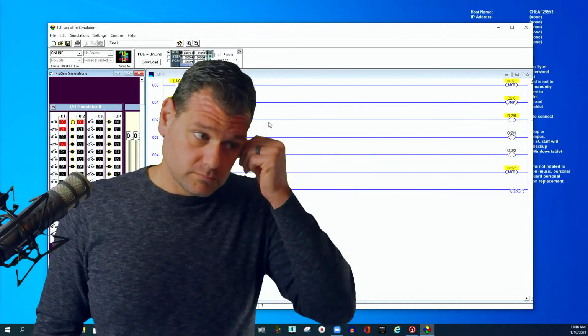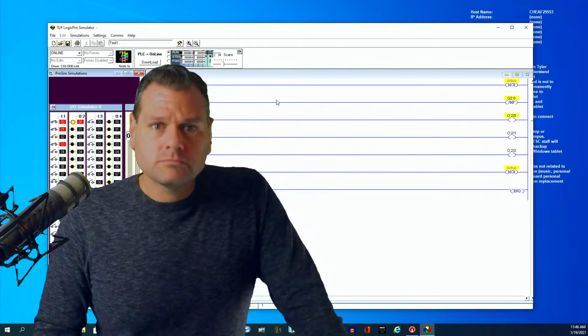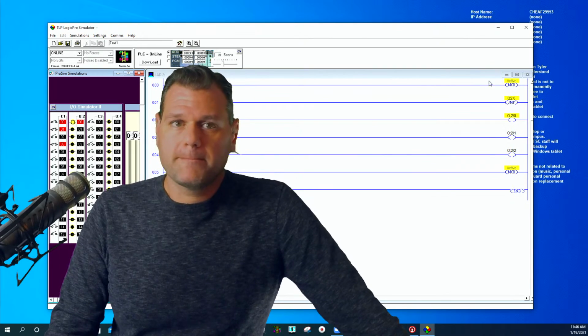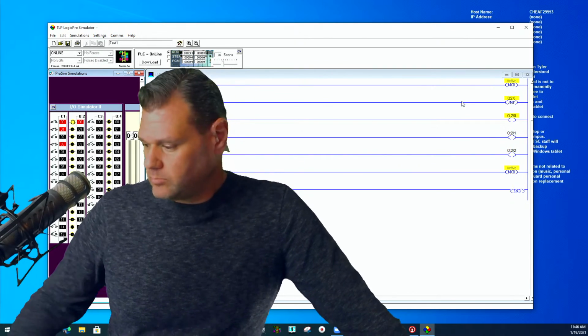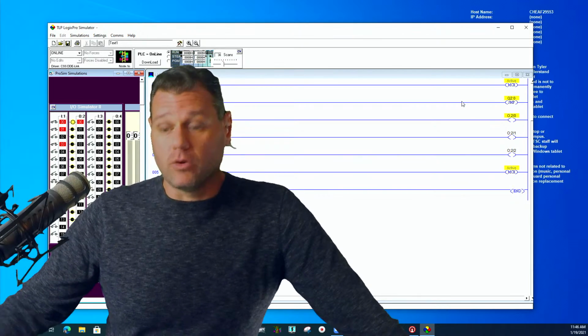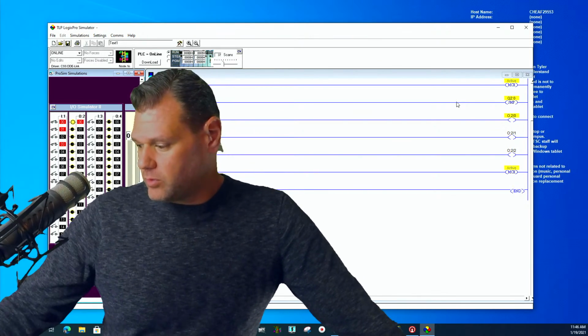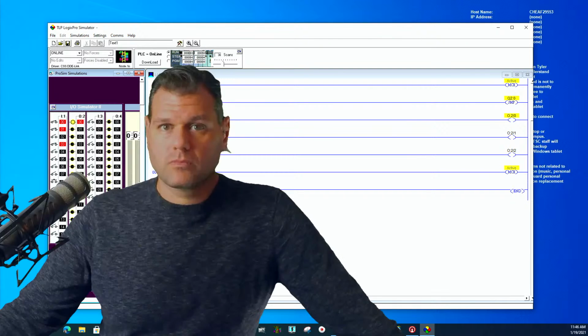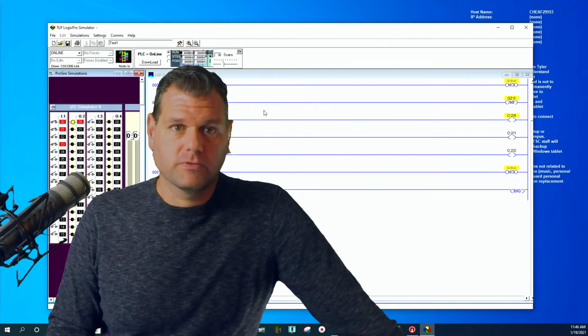So here is a question, and maybe somebody else is saying it, maybe they're not. The MCR. By you putting a jump in the middle of that, is that not creating a subroutine? No. Maybe I missed something along the line here, but I thought for sure when you go to the master control relay, everything in that zone becomes operative only within the master control relay. So your normal program is going to work outside of that particular zone. Correct. Is that correct?